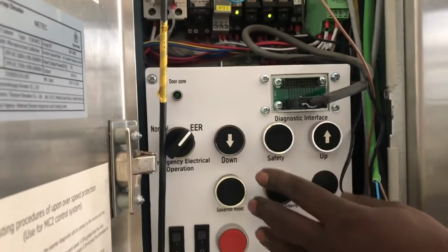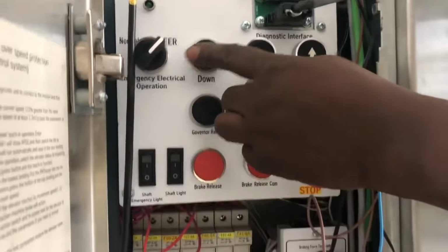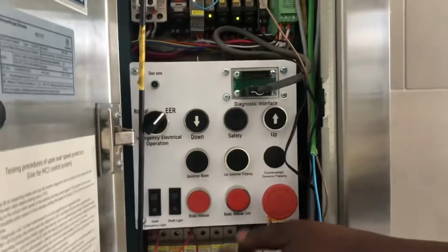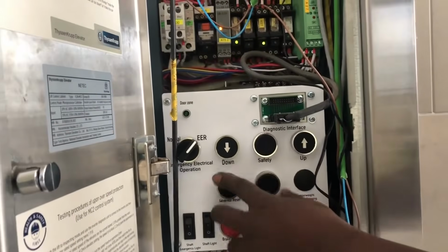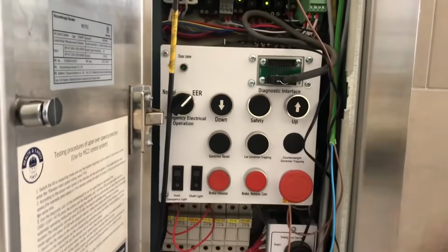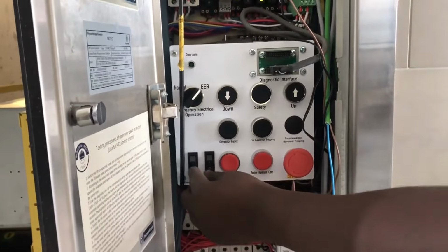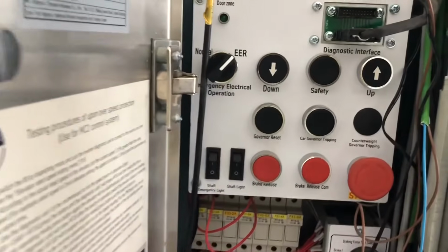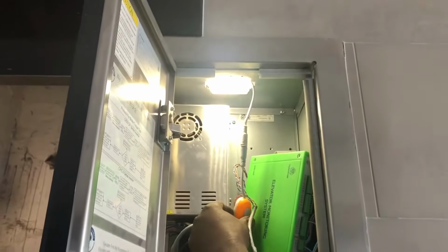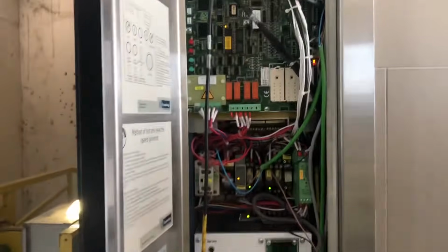These other buttons are very sensitive and we don't normally use them much. We normally use this one, and this one. This one is the common. This one, and this one, these four, we normally don't use as much. This is the stop switch. The stop switch is normally to cut off the elevator, so it doesn't move at all. These are switches for shaft lights and emergency shaft light, just like this one, for when the building has low power and the lift is stuck.